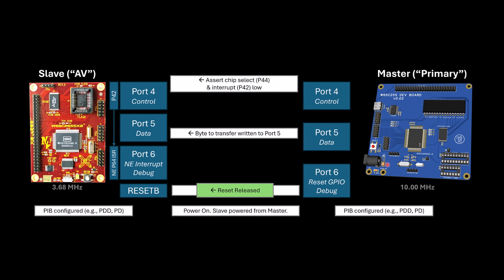Now, without PIB, there is no pin on port 4 that can do edge detection for interrupts, either a rising or falling edge. So that's a problem. Now, it must be that in the hardware for PIB, P42 maybe has interrupt edge support, but that's not something you can programmatically work with other than enable or disable it, as far as I can tell.